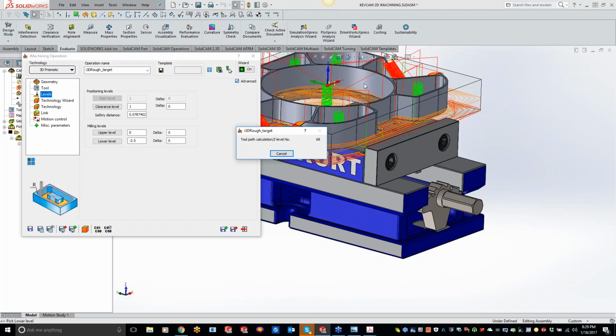And for the floors, like right here, we have a floor finish. It's not going to gouge into that material whatsoever. So you'll never have to worry about, let's say this pocket is 1.5 deep here, but you told it to go -2.5. It's not going to go through your SolidWorks model and gouge, or I'm trying to think of the word, violate the boundaries of that floor level. Is that what you're kind of asking there? Yeah, and I think that's what he was asking for.